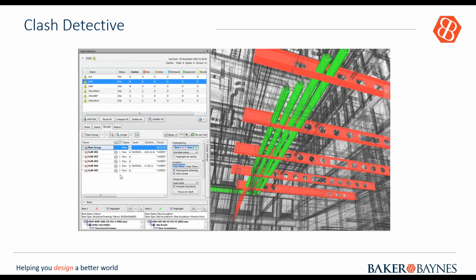At the bottom of your screen, this is where you get a list of your clashes, and they're listed according to their magnitude. What you're seeing on this screen here is clashes that have already been grouped. On the right of your screen, this is what your drawing or coordination model would look like with the clashes from all the different disciplines. This clash report has already been grouped.